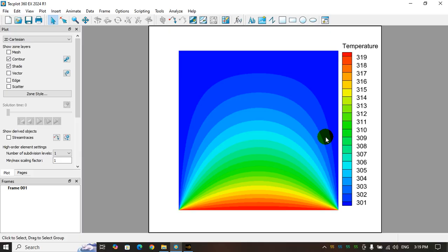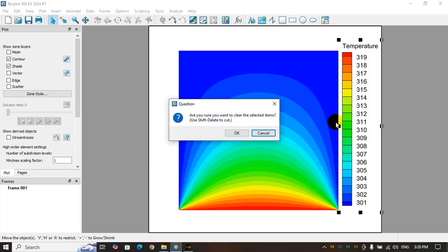So this is a good figure that you can have, but some projects make you have many different figures in many different contours in one figure. So I want to show you how to make multiple contours in one single figure in order to publish those kinds of figures in a paper. Let's do this again. I just delete this one. I can right click on it or hide, or while I'm selecting, press the delete button here, and OK.